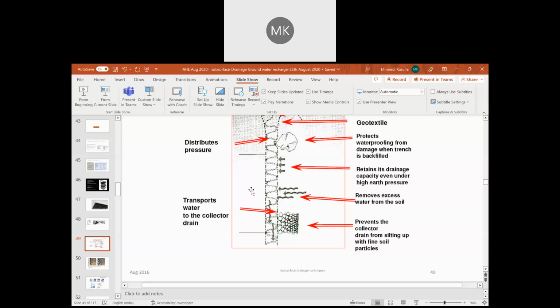Waterproof: if one side is an impermeable geomembrane, what are the properties of that geomembrane? Its wide width tensile strength should be greater than or equal to 13.5 kilonewton per meter. CBR puncture resistance is important for a geomembrane. Geomembranes are impermeable. They can be smooth or textured, but they can get punctured very easily. So CBR puncture resistance is important.